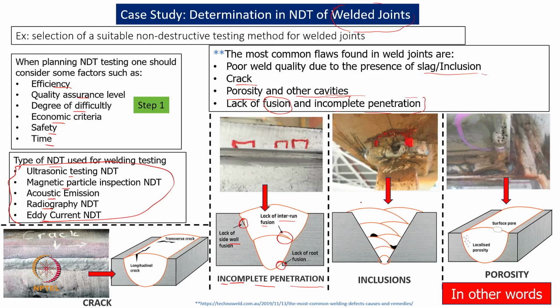There is a possibility that some inclusion keeps coming, maybe because of dirt, because of oil, or because of some other sources. So, inclusions are possible which come along with the weld junction. We know that because of the inclusions there is a possibility of a crack, and that it will grow, and there is a possibility of corrosion, or maybe crevice corrosion, which happens. So, that will maybe initiate.